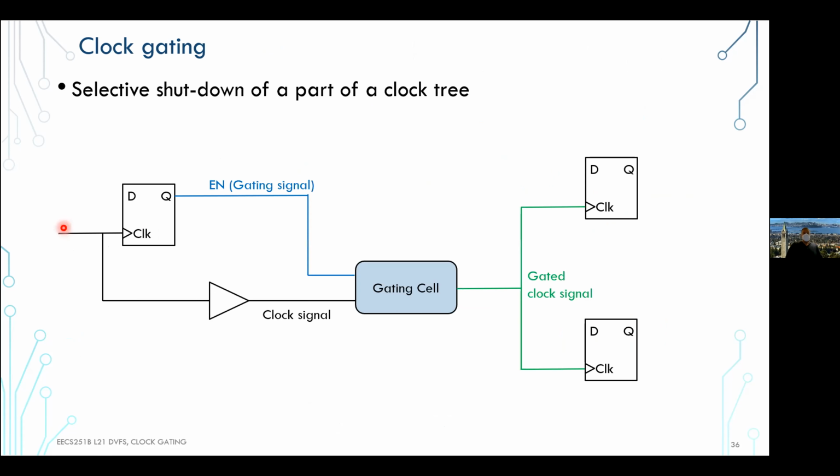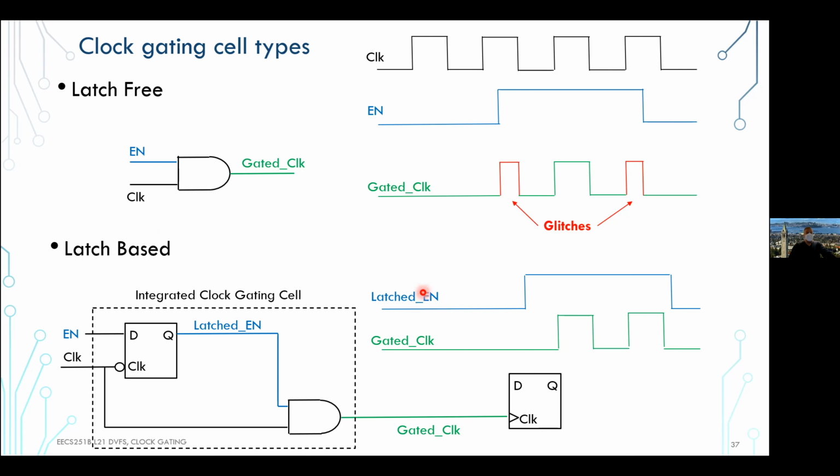Of course, if I go back here and just add an AND gate, a naive way to do it, we could hope it accomplishes the task. But let's see what the subtle problem with it is. If I take just the AND gate and stick it into that gating cell, you get a situation on the top. You have a clock that's happily coming into one of the inputs.